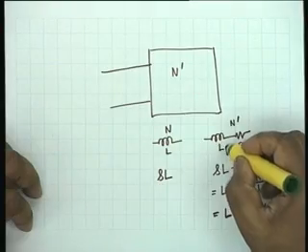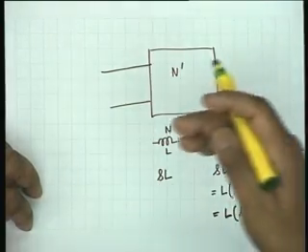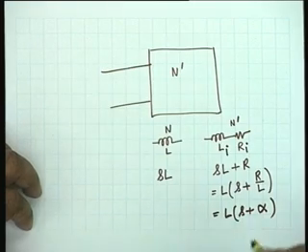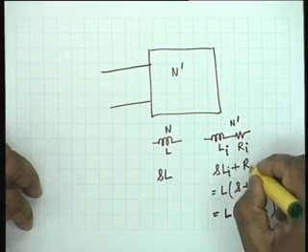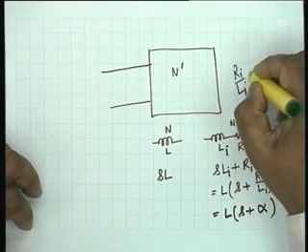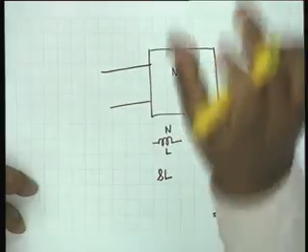In other words, what I am saying is that each inductor Li, where i goes from 1 to n, is augmented by a resistance Ri in such a manner that Ri by Li is a constant equal to alpha. We can do that. Every inductor that I find, I add a resistance alpha times Li. That is all that is meant. In series, I add a resistance.